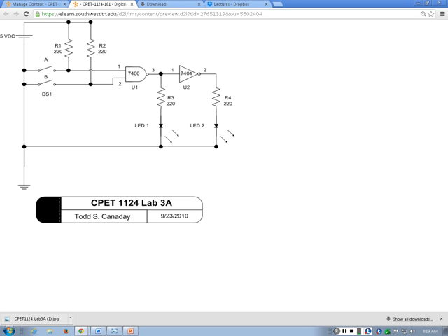Okay? And then on and off, those configurations will be coming. You know, when you have 2 inputs, how many combinations can you have? 4, right? 0 0, 0 1, 1 0, and 1 1. So you'll be basically building the circuit, and once you build it, you just change those switches and record the result. And then, what do you have? You now have a truth table, right? We all know the truth table. Every digital circuit will have a truth table, and from the truth table we will know exactly whether the circuit is working right or wrong.